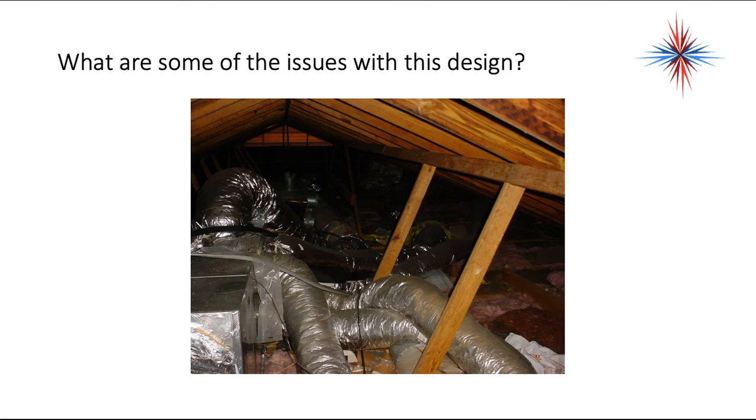This is an example of a ductwork system in an attic. How many problems can you find just looking across here? I see return ducts that are not pulled straight. I see tape coming off. I see insulation on that bottom piece of ductwork. I see a crushed piece of supply flex duct. I see possibly another crushed piece of flex duct to the right of that joist that's up and down. I see some connections, if you look closely back here, that are not taped or masticed. So this system is leaking badly.